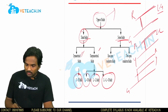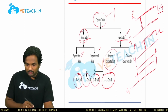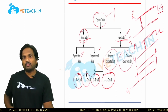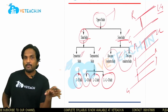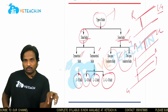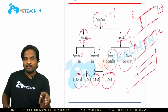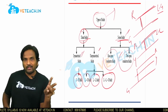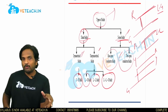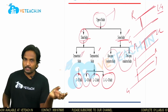Moreover, series faults are classified into two types: one open conductor faults or two open conductor faults. That is how we differentiate the faults in power systems. There are shunt faults, which are classified into symmetrical and unsymmetrical faults. Unsymmetrical faults are again classified into line to ground, line to line and double line to ground faults, whereas a symmetrical fault is also called a three-phase fault.